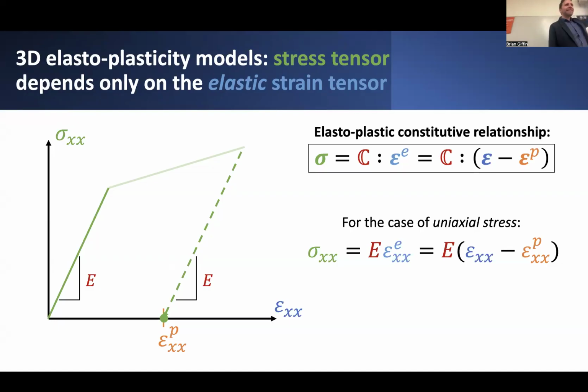Okay, so in likeness to the way that we developed our regular isotropic elasticity models, we can suppose that there's some linear relationship between stress and strain, adopting the same conventions that we had previously by supposing that we can define this rank 4 constitutive tensor. Equivalently, if you want to arrange the stress and strain tensors into the format of vectors that contain 6 independent components each, then we could choose to instead format this rank 4 tensor into the format of a simple 6x6 matrix.